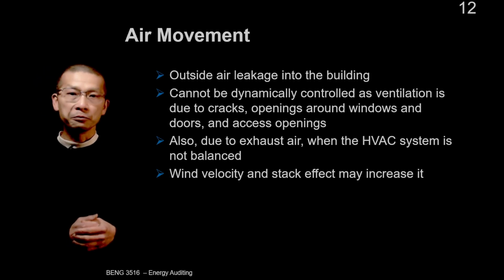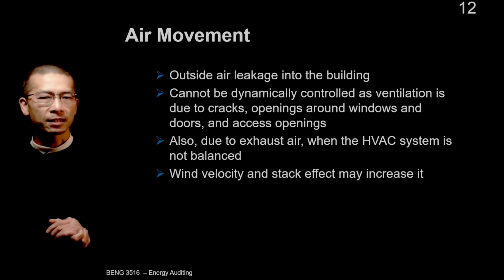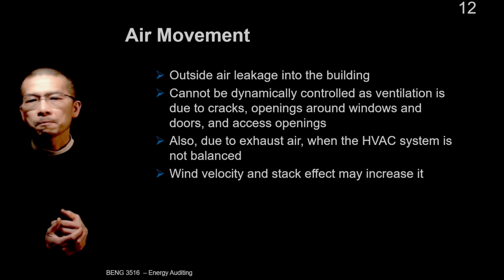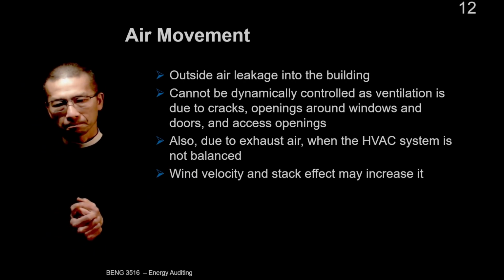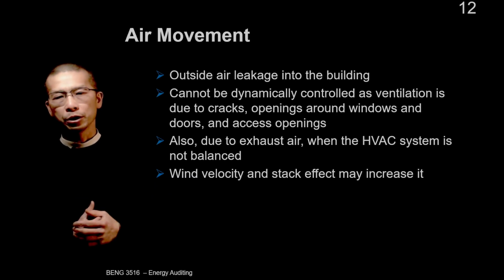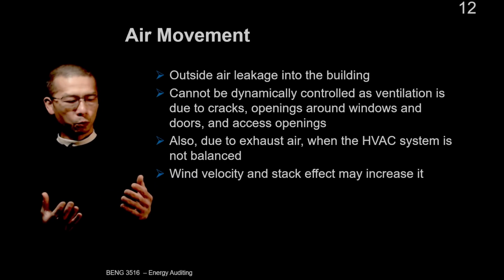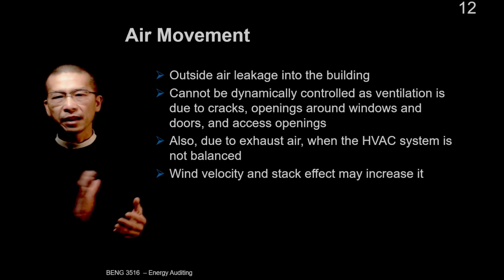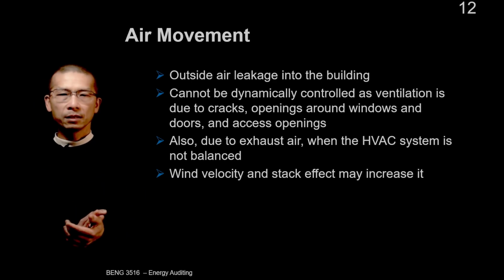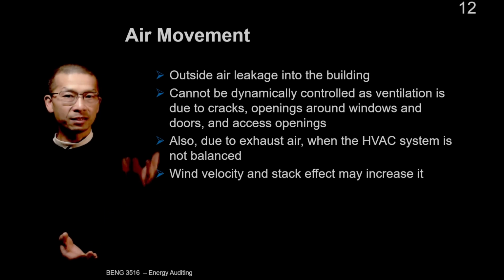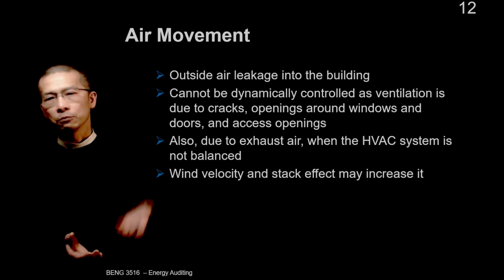Also, we have to respect the laws of physics: wind velocity and stack effect. Wind creates a high pressure zone on the side of the building, where the wind physically pushes air through the wall. Stack effect acts like a chimney, because warm air is less dense and rises.